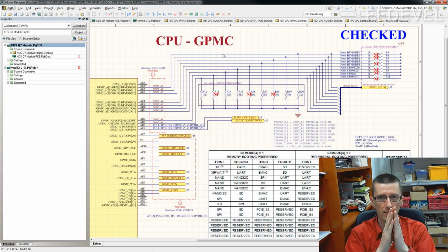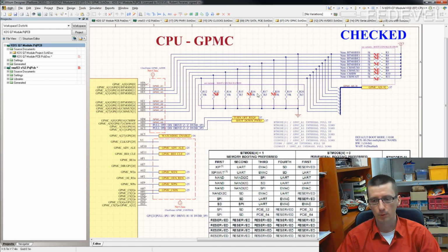So if I place them very close, because it's a very simple connection, I can save space for some other more important things. That's the reason why I try to place all these bootstraps and pull-ups, pull-downs there when they should be here. Be careful, because some pull-ups or pull-downs, if they are used as termination, may need to be placed on the other side of the track.